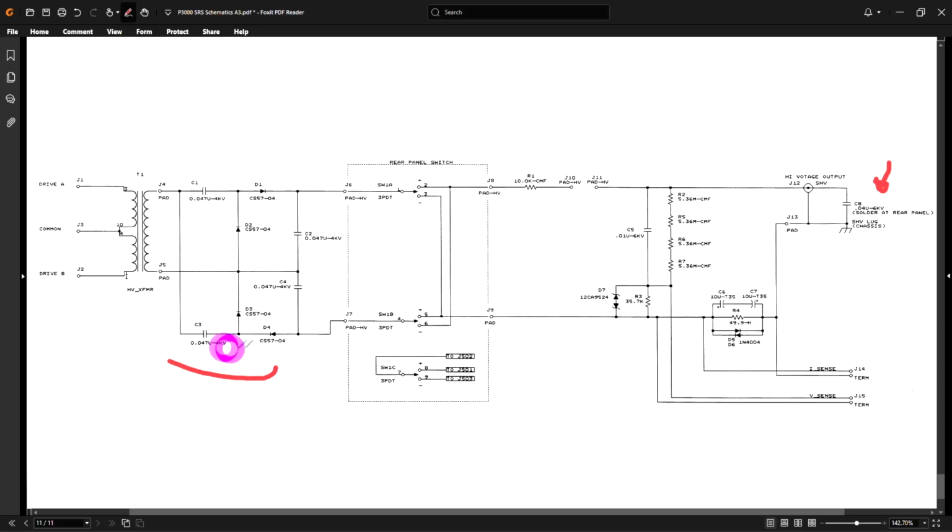But of course, all of this means is that you're going to get half as much current as you could get from the 2500 volt version, and 1/4 of the current you could get from the 1250 volt version. That's because there's no magic here. These voltage doublers with capacitors and diodes just simply trade off current for voltage and vice versa. That's all that you can do really with these things. Essentially, the power remains constant, but it allows you to go to higher and higher voltages.